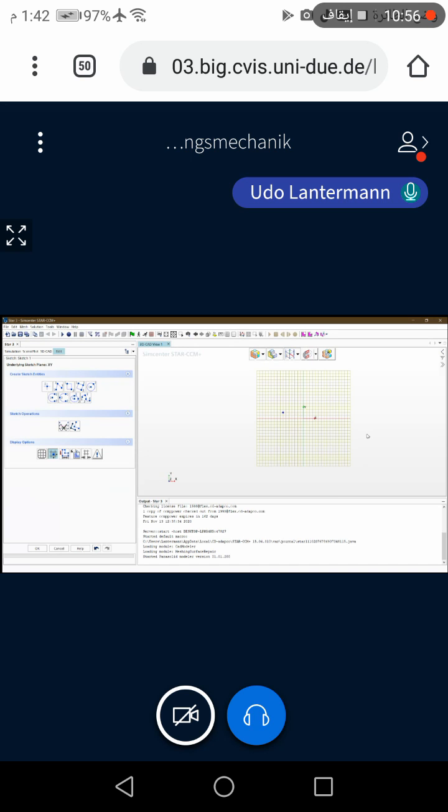So the next step, now we will change the coordinates. So you have to click again with your mouse on this node, and it will appear on the left-hand side, the coordinates of x and y direction. In my case, it's minus 0.07 in x direction and 0.02 in y direction. Okay, this we will change now by hand.